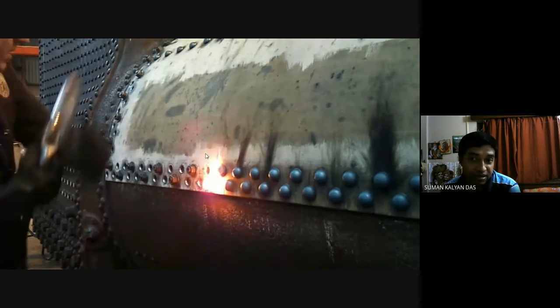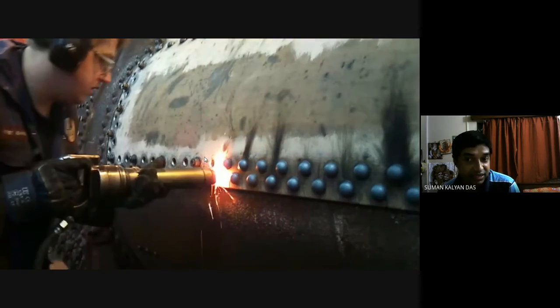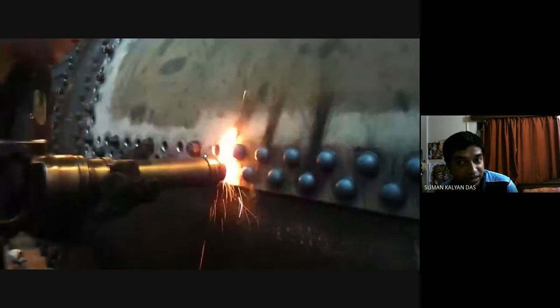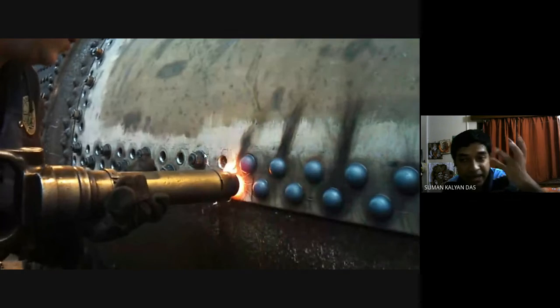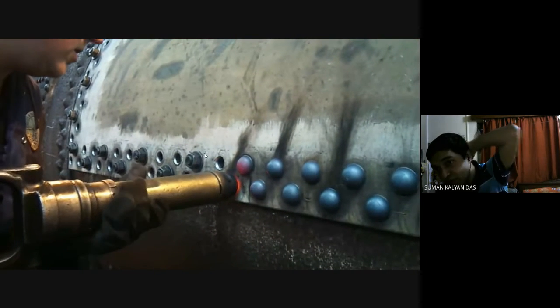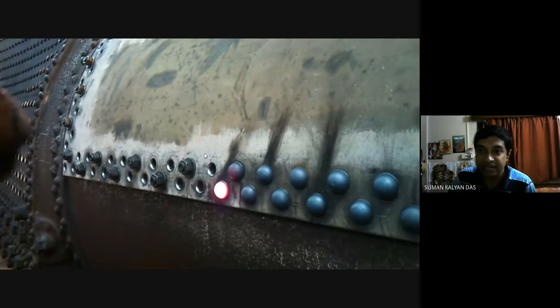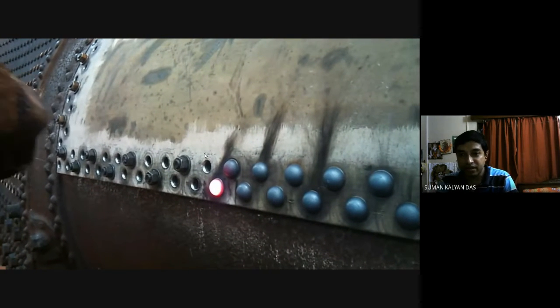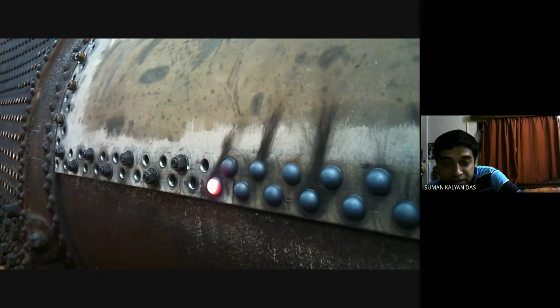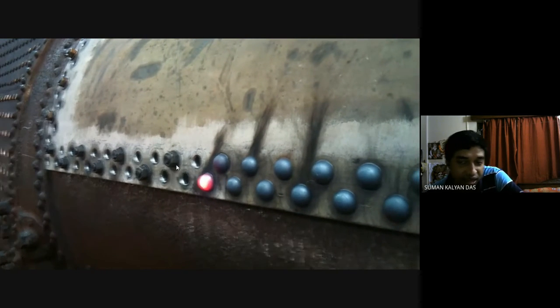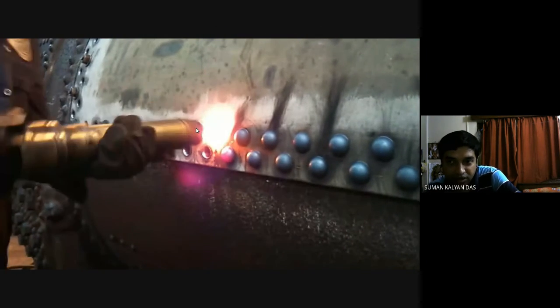Obviously, for a boiler, leak proofness is a very serious thing. You need to have the boiler leak proof. Otherwise, if you plan the pressure of the steam to be of some megapascal, and if there is leakage, you will never attain that amount of pressure. And bolt and screw joints are not quite effective in providing this leak proof type of joint. So that's why these are just for temporarily holding the plates.